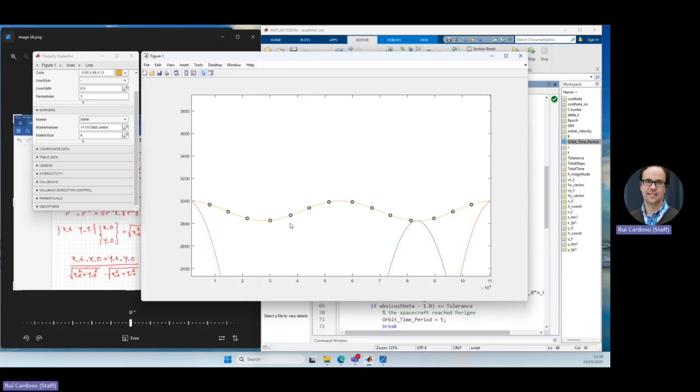Don't put just GMAT screenshots, that's it. Try to explain how you model in GMAT. You said, for example, use a Cartesian instead of the Kepler. Well, explain that. Explain your inputs. If you use the Kepler things, explain what Kepler inputs you did, assumptions you made.